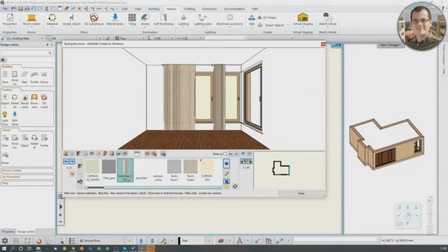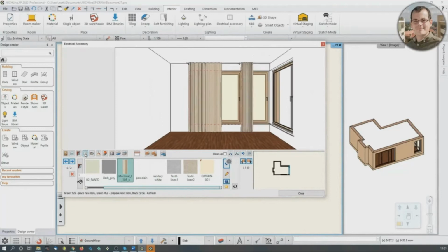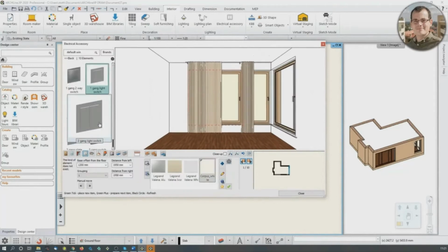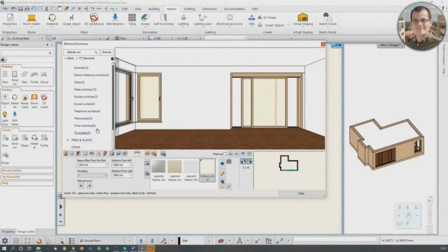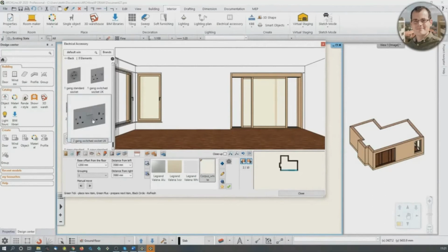The next task is basically how to keep on coloring things, and let me just go on my cheat sheet and talk about wall colorings. Or before we do that, I think the next step would be switches and sockets. Now, what we have to do, you might have already guessed it, first we have to find the wall on which I want to work, and then I have to find the element I want to position. Let me hit back and start with a socket. Socket outlets, very standard European socket. If you want to use the English one, we have them here as well.